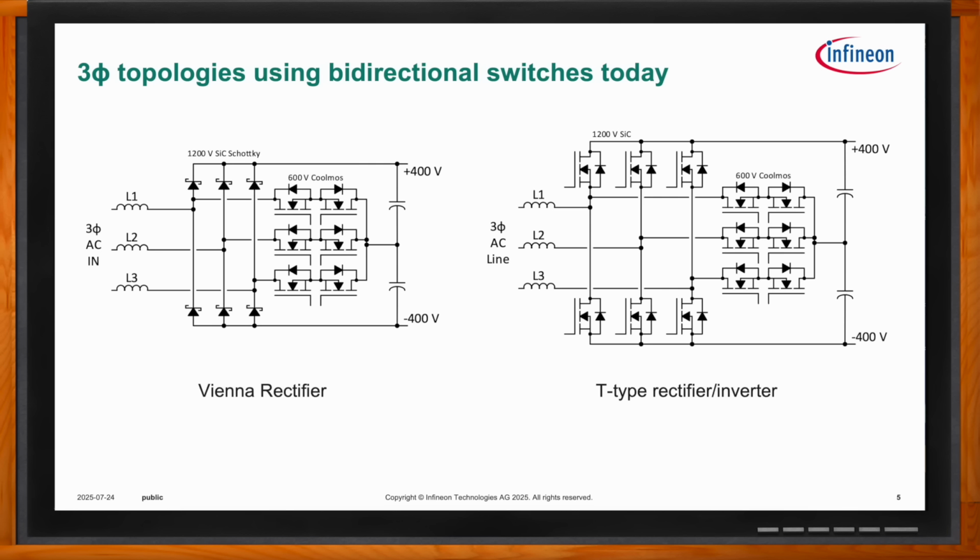On the other hand, if you want power flow to go the other way, like for a regenerative system, or let's say a big battery system where I want to connect a battery to a utility, a microgrid, and I want power flow to be able to go either direction, then I could use a topology like this. Now I can control those rectifiers and have them on or off whenever I need in order to make power flow go either direction.